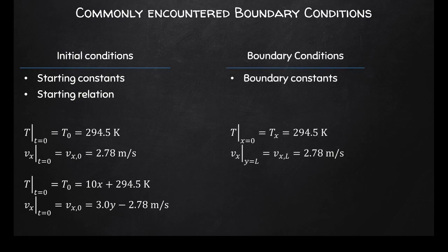Now, we can also have boundary conditions, and this is what I have been referring to when we were discussing the initial conditions. Boundary conditions are conditions that don't typically change, whereas initial conditions could proceed to some final condition. Typically, you would deal with this in unsteady state heat transfer.